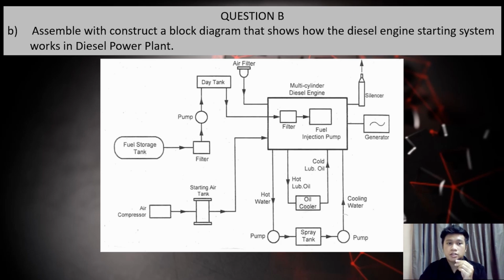The diesel engine is the main part of a diesel power plant. Engines are classified as 2-stroke engines and 4-stroke engines. Engines are generally directly coupled to the generator for developing power. In diesel engines, air admitted into the cylinder is compressed. At the end of the compression stroke, fuel is injected. The fuel is burned and the burning gases expand and do work on the piston. The shaft of the engine is directly coupled to the generator. After combustion, the burned gases are exhausted to the atmosphere.